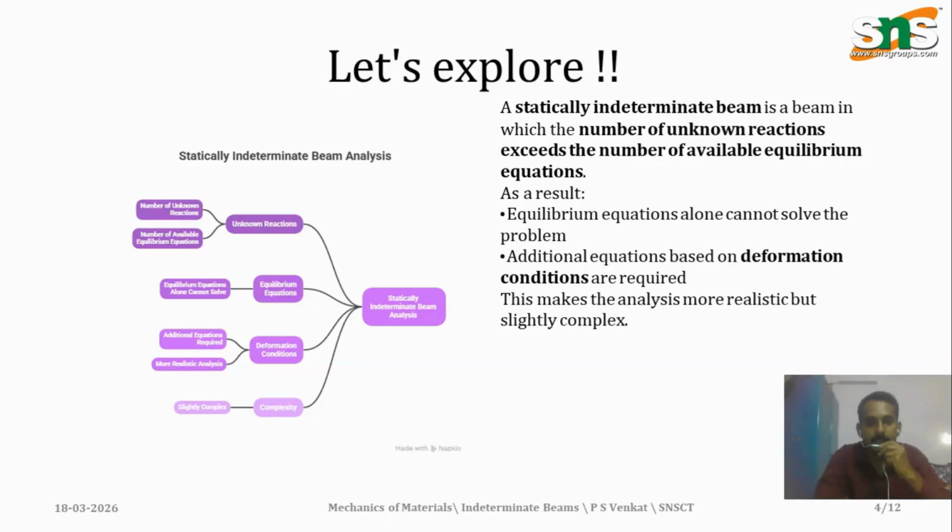For example, consider a beam fixed at both ends. You cannot determine reactions only using equilibrium conditions. You must also consider how the beam bends. So indeterminate analysis combines statics, material behavior and deformation concepts. This makes it more realistic.